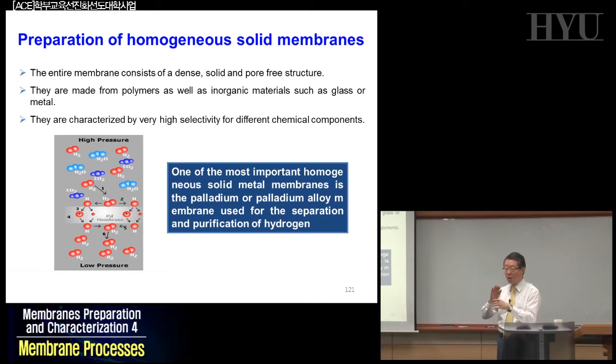Okay? Water will block the pore, so that final property will be much more reduced due to the presence of this water. So what he's doing is that if we can coat a very thin layer of all-silica on top of this zeolitic membrane, then we can improve the performance of this zeolitic membrane.